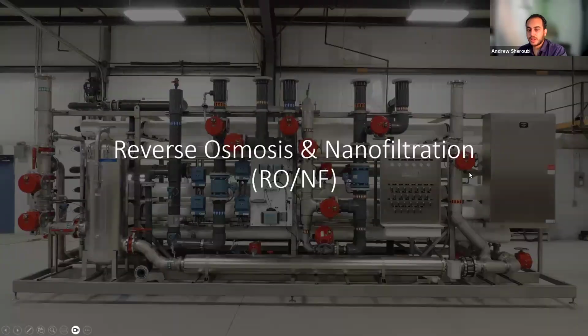And this is the first technology I'll talk about, the spiral wound membrane, which again, is reverse osmosis and nanofiltration. Now, reverse osmosis and nanofiltration, I group them together because there is no hard line about what is considered reverse osmosis versus what's considered nanofiltration. Reverse osmosis is just a tighter membrane, and nanofiltration is a looser membrane using the same technology. And I'll go over that in a couple of slides.